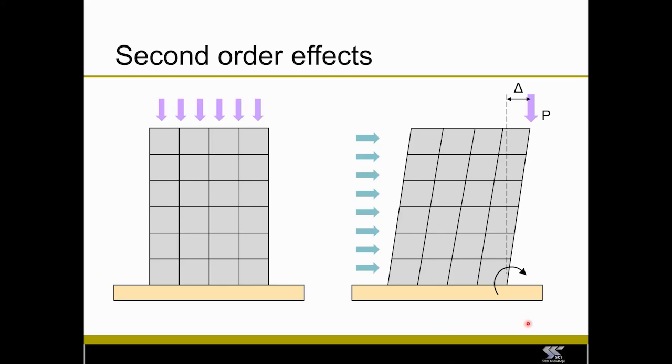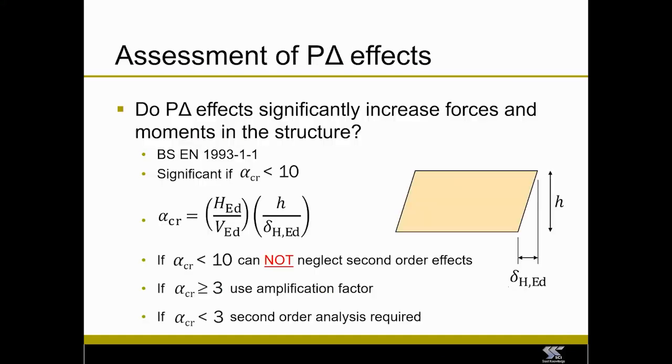So this image here is showing that whereas in the idealized situation we had a vertical load above the column base, here we've got it offset, and therefore that column base, if you like, is going to be subjected to additional effects, in this case shown as a moment, but there'll be other effects in the structure from these movements after the first order effects.